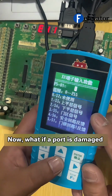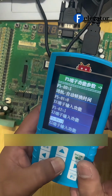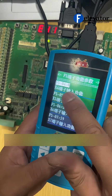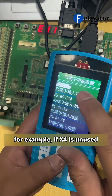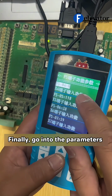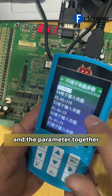Now, what if a port is damaged and you need to reassign it? First, set the original port's parameter to 0. If you don't do this, some ports may not allow modification. Then, physically move the wire from the damaged port to a spare port. For example, if X4 is unused, connect the wire from X1 to X4. Finally, go into the parameters and set F5-04 to 1. You have to change both the wiring and the parameter together.